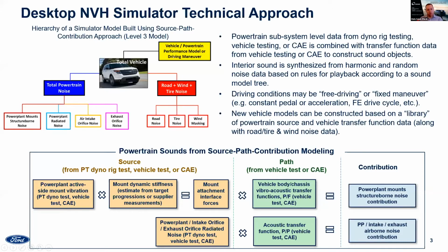The real-time driving conditions are governed by this performance model, which can be free driving or a predefined fixed driving maneuver. The way the simulator works is it takes the source level data, the time signals, and decomposes it into harmonic and masking components. Those harmonic components are related to the rotational speed of the engine, and the random noise is everything else. The noise is then resynthesized in real time based on the driving conditions governed by this vehicle performance model.